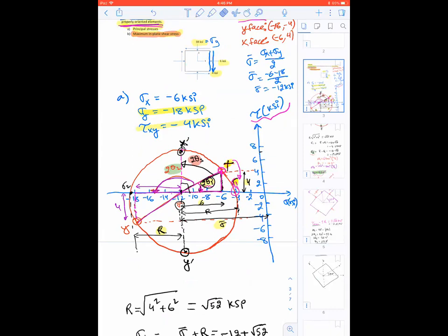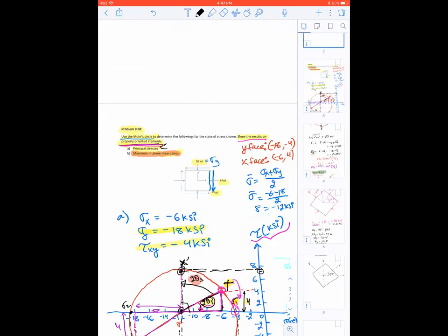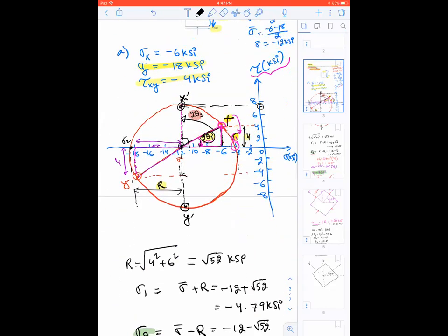So if I clear these things up, you can see that if you go down, this will read your normal stress, and this is going to read your shear stress for this point. And similarly, last time when you were asked to find these principal stresses, even if you forget that there is no shear stress, you know that this point is your principal stresses.